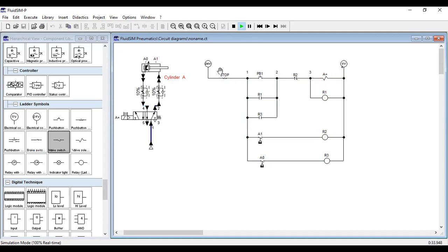That is why we create the start push button. In this case, the normally closed stop push button is not functioning because once you release the stop push button, immediately the system will start by itself. So that is why we have the start push button, to enable the system to start when it is triggered by the operator.